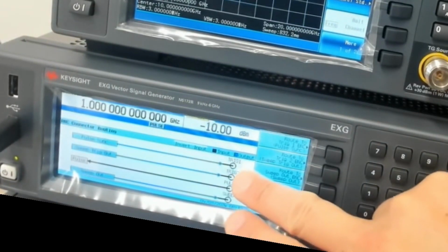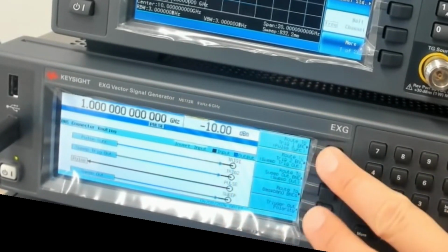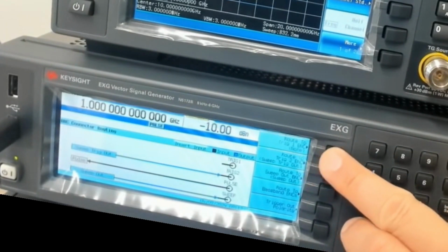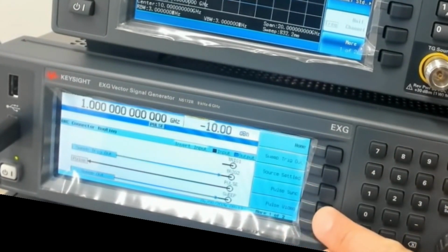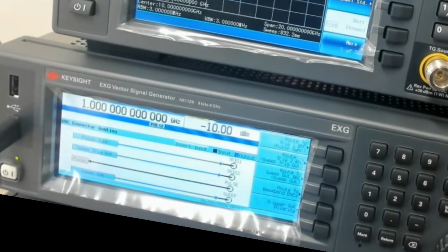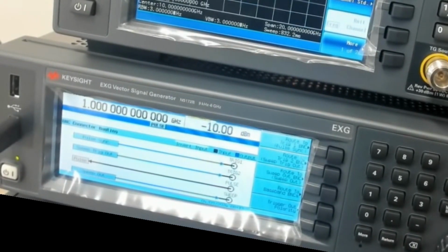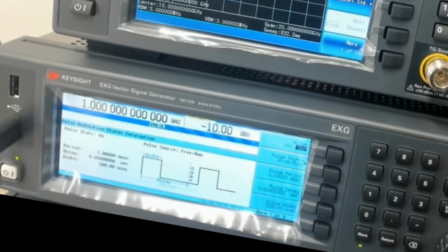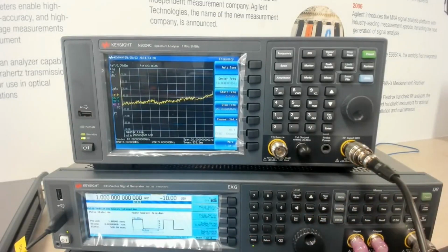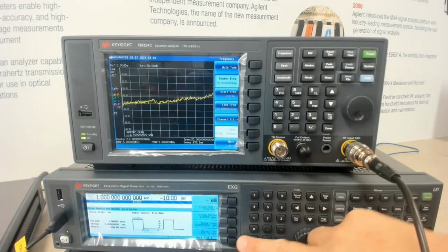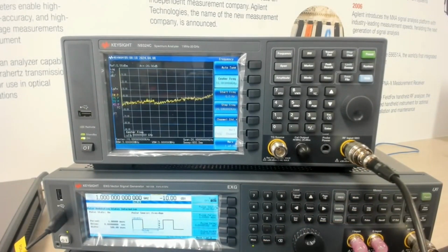By default, trigger 1 is not connected to anything. So this is how it looks by default. We have to route a pulse sync to trigger 1, because I use trigger 1 as the output to the spectrum analyzer trigger in. With that done, I will set the pulse period to something bigger instead of 4 microseconds. I set it to 1 millisecond and 500 microseconds pulse width.